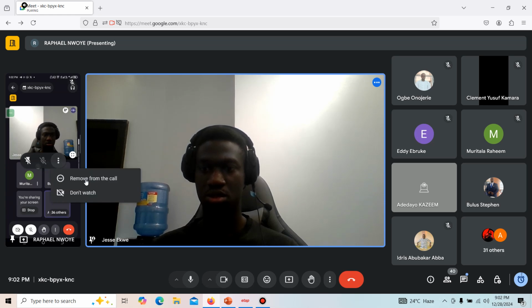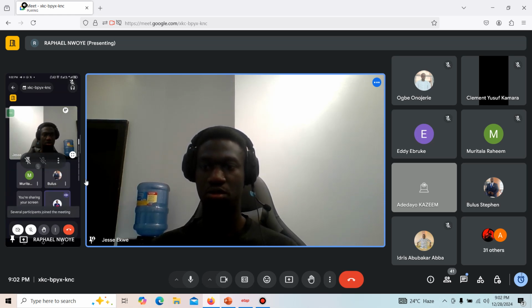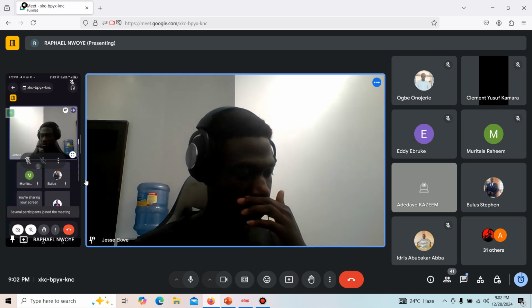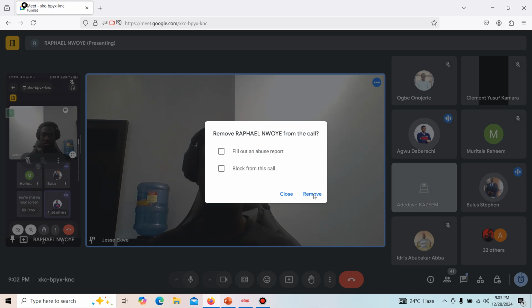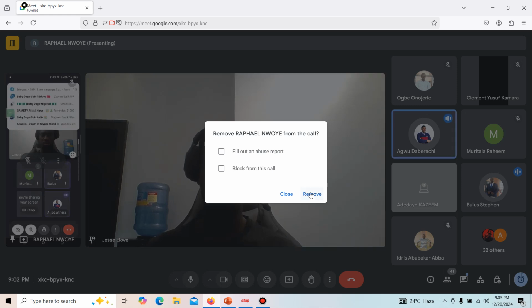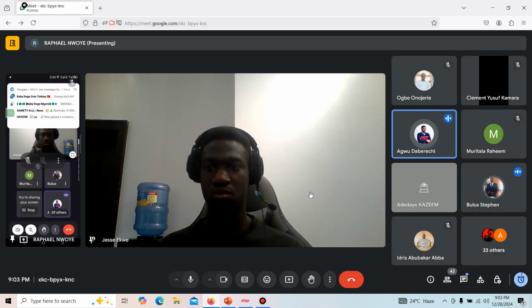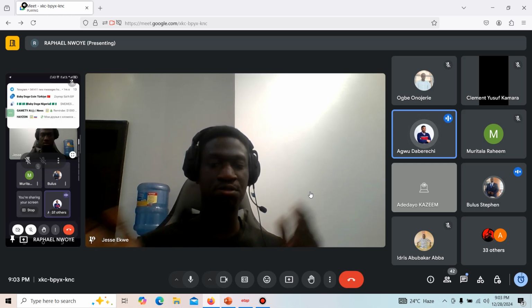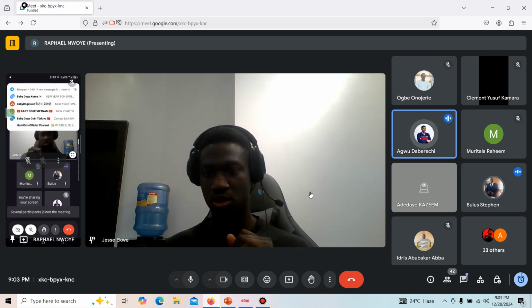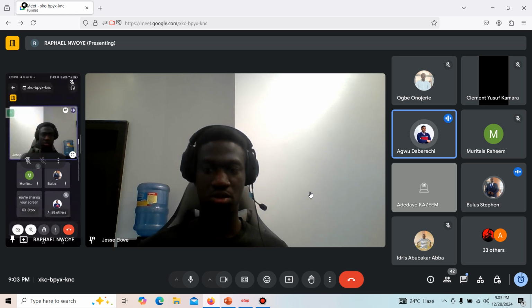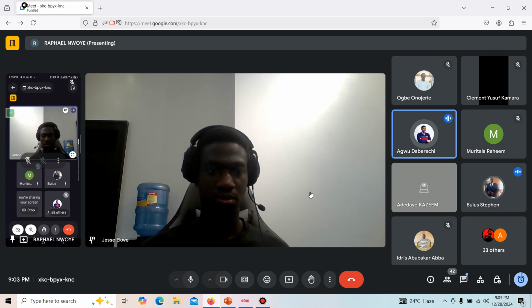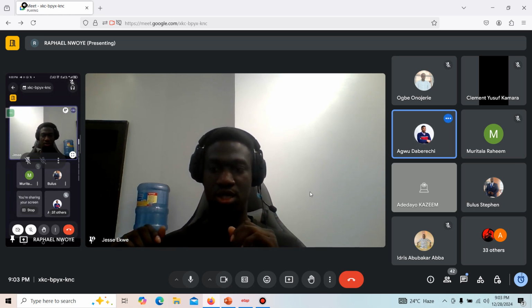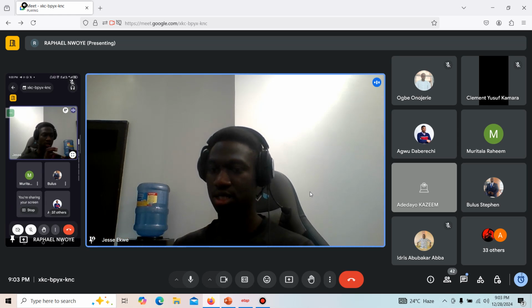Can I ask a quick question before you continue? Yes, you can go ahead. In the instantaneous relay and time relay, there's 50 and 51 there. What do those two numbers mean? Okay, 50 and 51, so instead of saying overcurrent protection, we can just say 50/51. So 50 is a code, a standard.